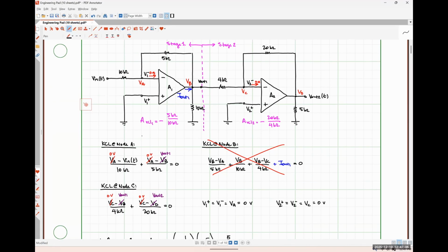When we did that, without doing any actual circuit analysis whatsoever, we just recognized what each of those individual amplifier stages were and how they behaved. The reason why we can do this is because we know that these configurations have really, really large input impedances and really, really small output impedances. So when we chain them together like that, all of our signal essentially survives and gets passed through to the next stage.